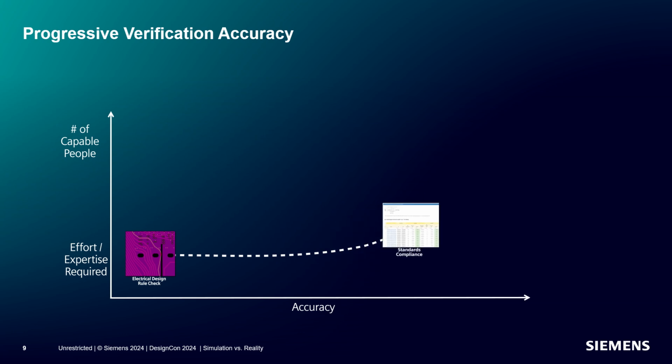The next step is standards compliance analysis. This looks at the system level interconnect to check it against protocol requirements. This helps us to determine if our issue meets the compliance characteristics of the issue at stake. Did a channel pass or fail? If so, by how much? This can be run using one of absolutely hundreds of protocols and variants that Siemens supports, 235 at our current count.